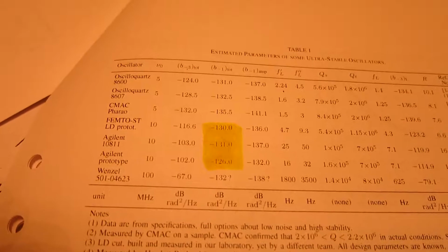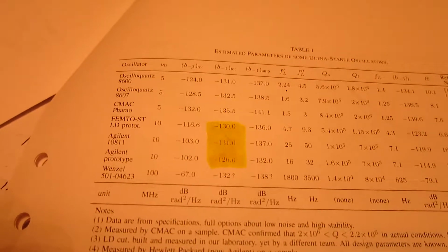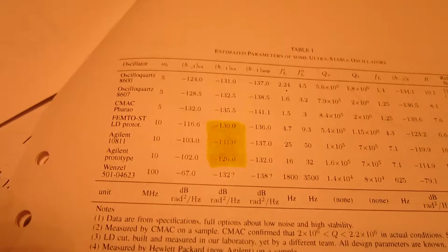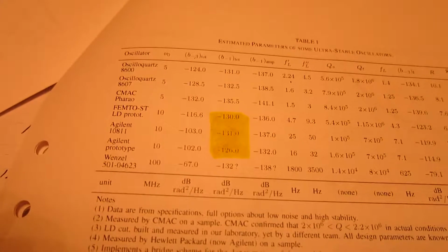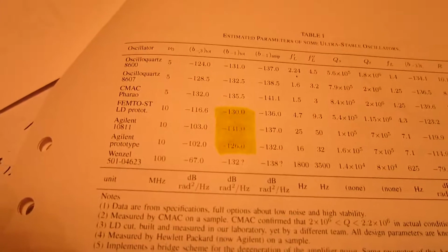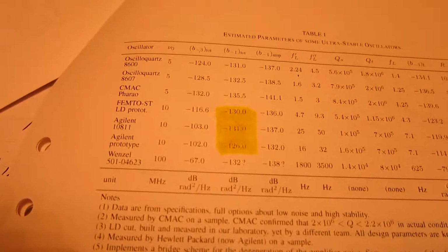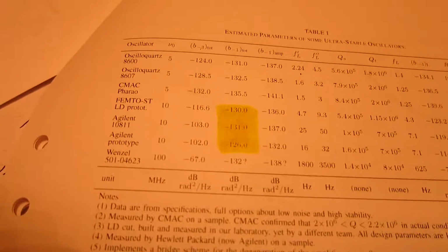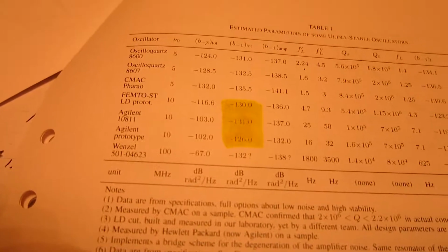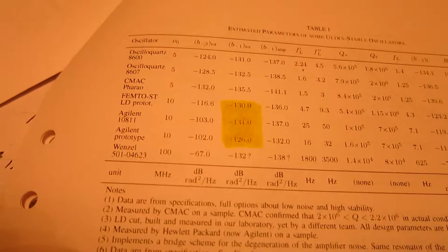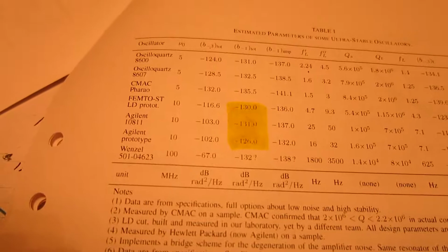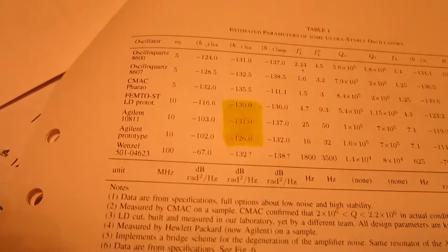Atoms are moving in crystals from temperature, and this will change the size of the crystal somehow, and it seems to be a property of the material. So having more crystals in parallel means the flicker noise goes down as a square root of the number of crystals, because the noise in the individual crystals is uncorrelated. Well, that is my guess as a conclusion of what I have found in this study and what I can read in this paper.